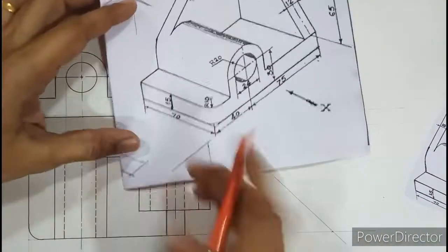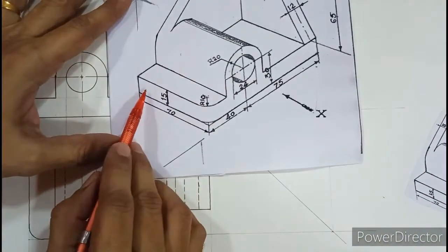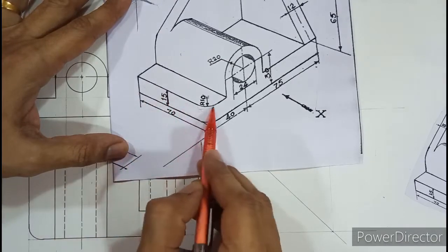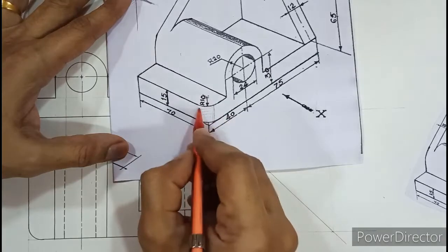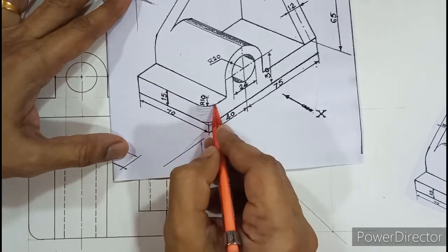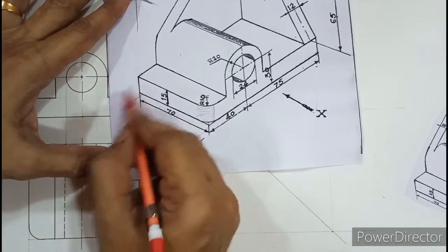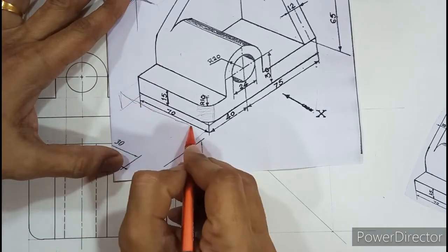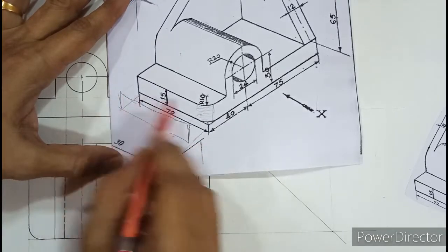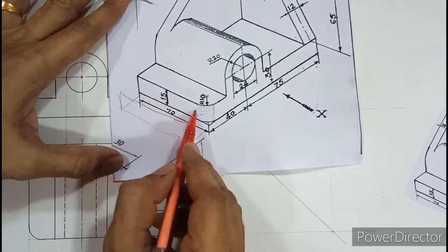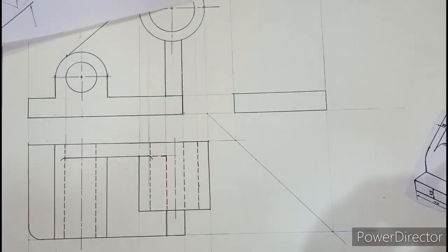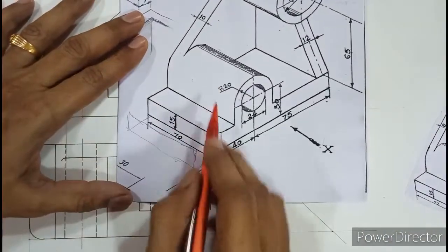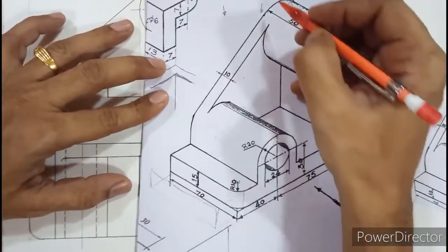Okay, so hope by this time it is clear that this is a flat surface, whereas this is a curved surface. So at the max, you can see curved surface till here. So even this curved surface in the side view, when you project, it will be seen as a rectangle only, isn't it? So up till the curved surface, it will be seen as a pure rectangle. So straight plus curve is a total rectangle. That is what we have drawn here. So once this is ready, let us move up now and carefully observe.